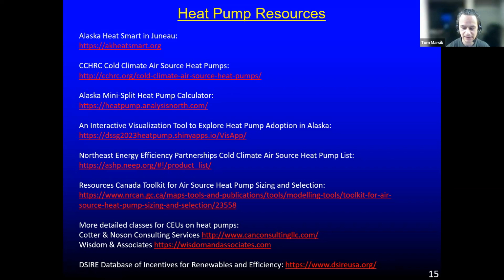So there's a message in the chat for me, and that says, I'm struggling to understand the cost benefit since I still need a normal heating system. So that's a great question. So you still have a normal heating system installed in your building, which we need in a very cold climate, like we pointed out. The heat pump stops working at a certain temperature. So we do need to have a different heating system that's going to serve as a backup. But in those temperatures, when the heat pump is actually operating, it's lowering the amount of heat that the primary heating system is supplying to the building.